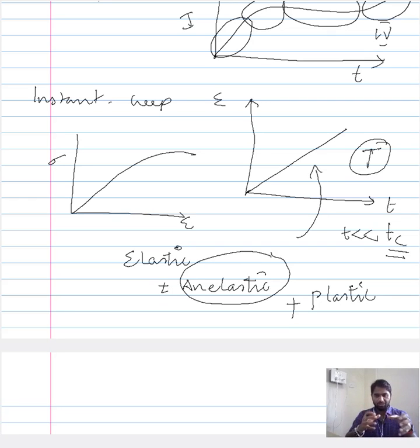Depending on the regions we are talking about, some region might exhibit an elastic change, some region, maybe along the grain boundaries in a polycrystalline system, might exhibit an anelastic behavior, and some regions with already pre-existing conditions might undergo plastic deformation. So, a combination of elastic, anelastic and plastic deformation is responsible for the instantaneous creep that occurs once you apply the load.